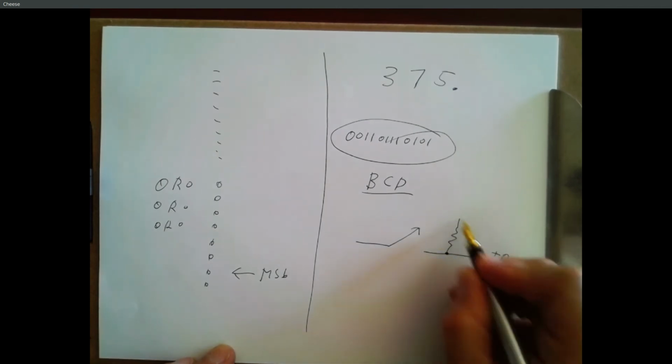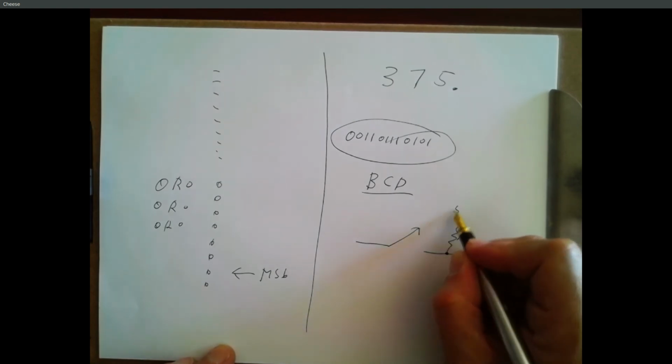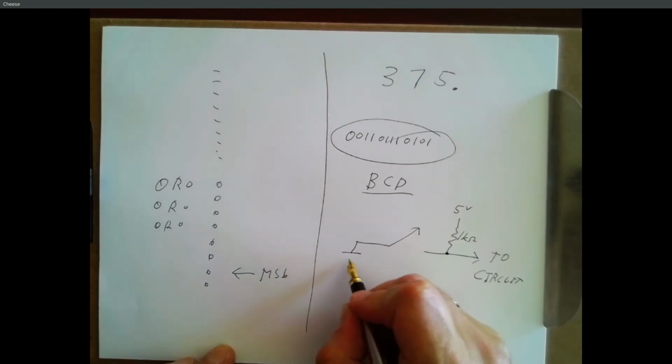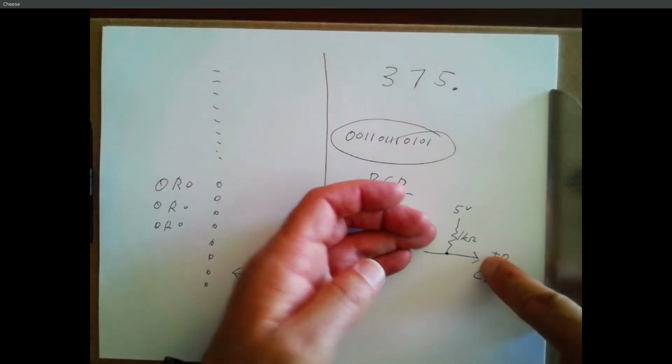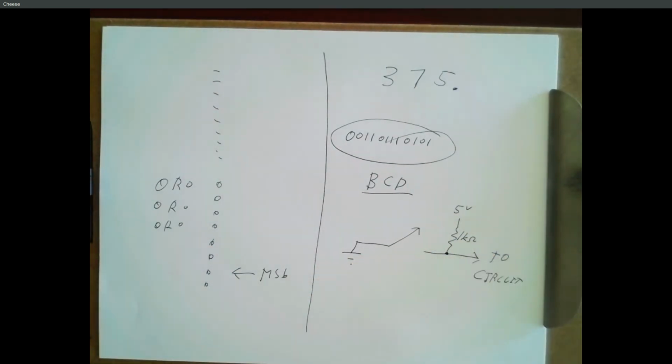So at that end, go through a 1K resistor and then use the switch to optionally pull that down to ground. So that's a pull-up resistor, right, as in FPGAs. If the switch is open, this is logic 1. If the switch is closed, this is logic 0.